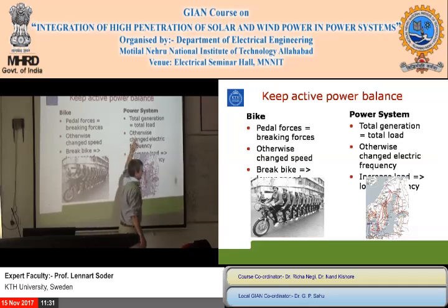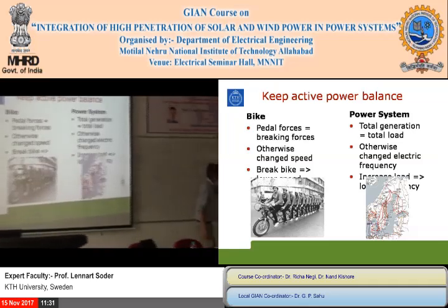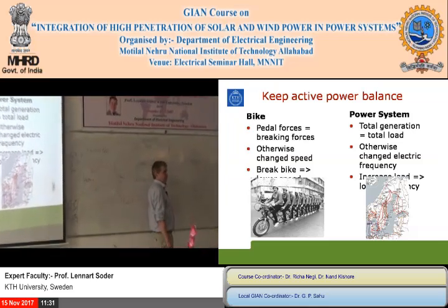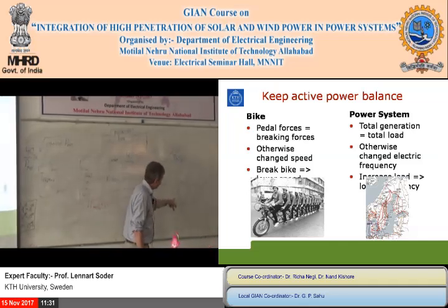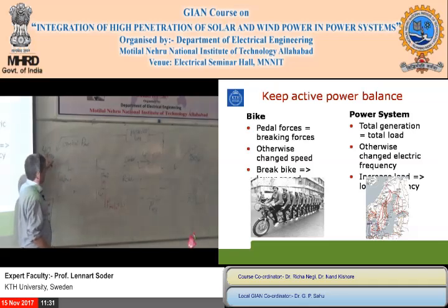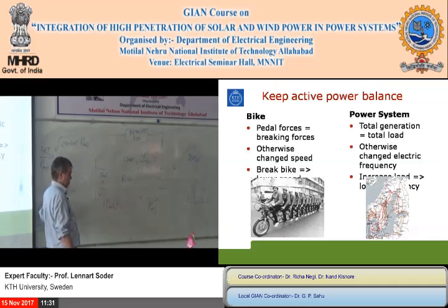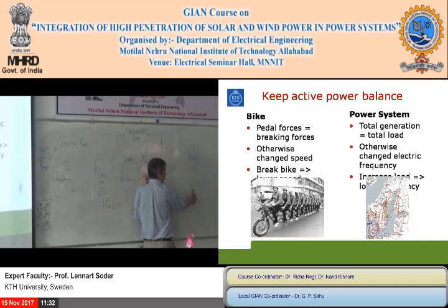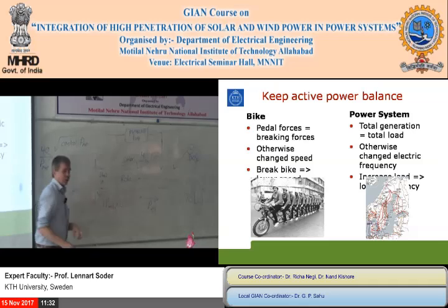And then I say otherwise here, because now I'm talking about the difference between the electric system, where you always have exact balance, and the mechanical system, where you not always have the balance. Here you are consuming 70, but in the initial part, what happened in the beginning was that you only produced 40. So here you can have an imbalance. On the mechanical side, from the mechanical power to the electric power, you can have an imbalance, but you can never have an imbalance here. Here you have always that the consumption, including losses, is exactly equal to the production. So this exact balance is in the electric system, not necessarily here, because here you have some storage, and that is what you have there.